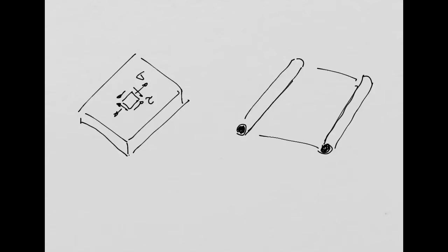And in our case, for the idealized structure, we said that the skin, which we assumed to have thickness equal to 0, only carries the shear stresses, tau, okay? And these booms carry the direct stresses, sigma, right? So if this is boom 1 and this is boom 2, this carries sigma 2, this carries sigma 1.